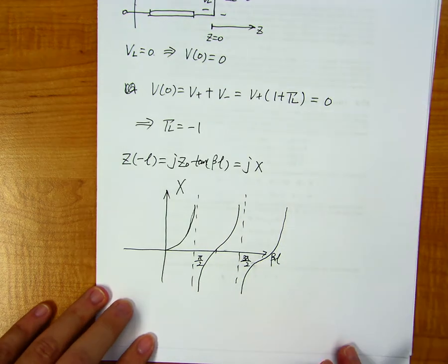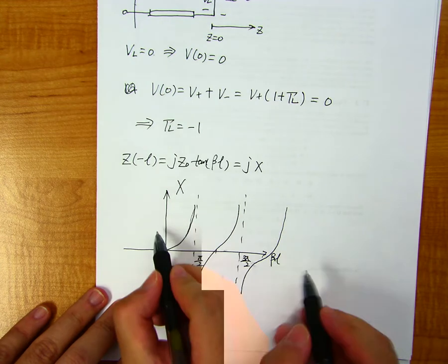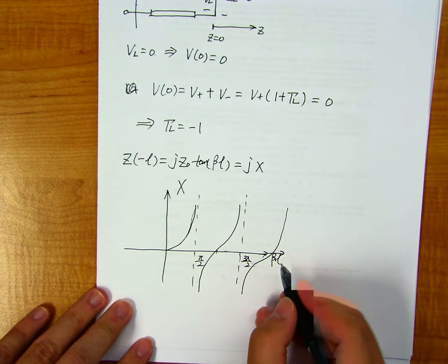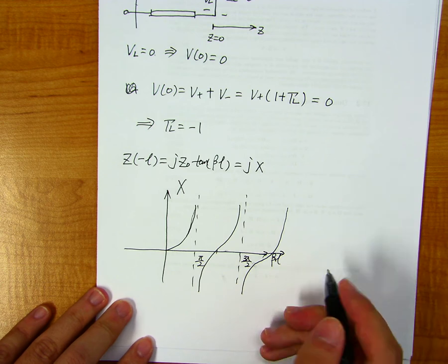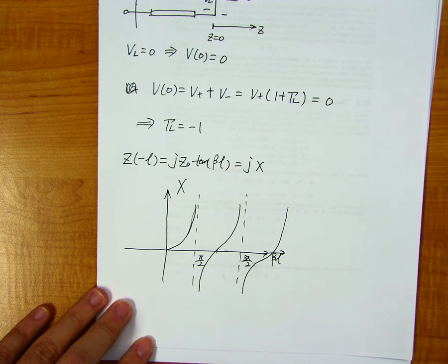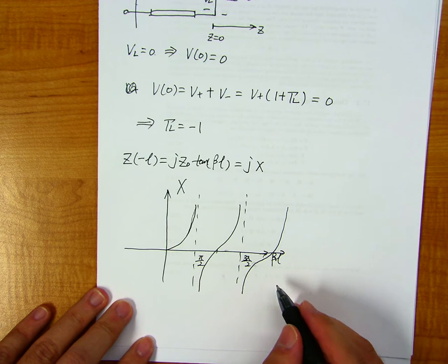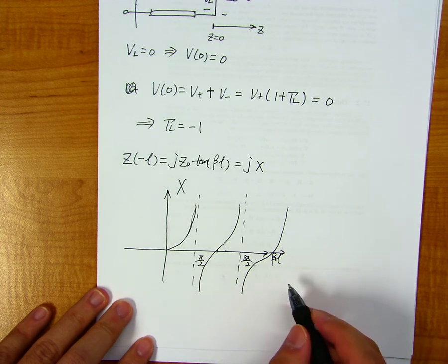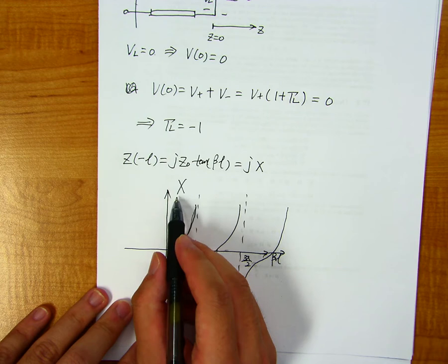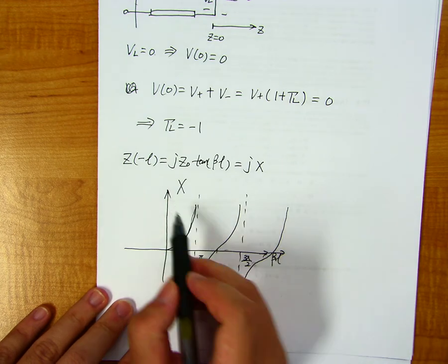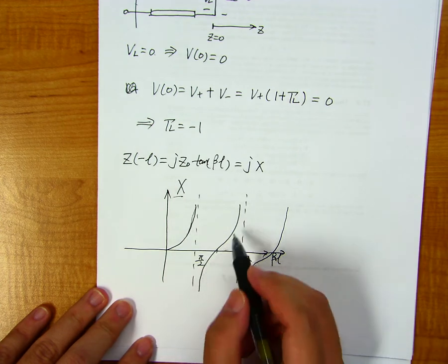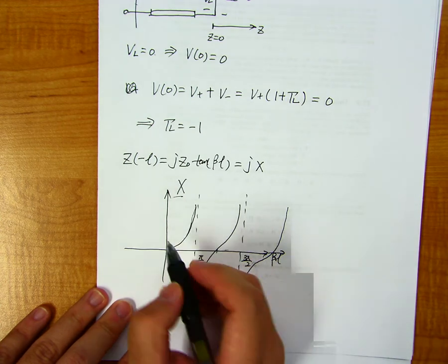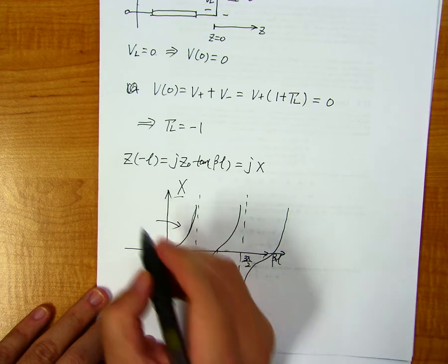Something like this, right? Which means if I change the beta L, which is also called the electrical length of this transmission line, because essentially we are comparing its actual length L to the wavelength, which is contained in beta. So if we change this electrical length beta L, the reactance X will change from a positive value to a negative value to a positive value to a negative value, which means this transmission line will behave like an inductor.